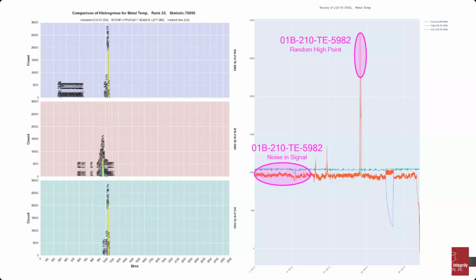One thing I wanted to mention: to attach the thermocouples, we use the capacitance discharge welding method, the same method you would use for post-weld heat treat, for example. We know it's not the most robust attachment technique versus a pad weld type of thermocouple. However, you're going to get a very quick response. So we're trading off reliability for a quick response and also cost. It's a lot lower cost.